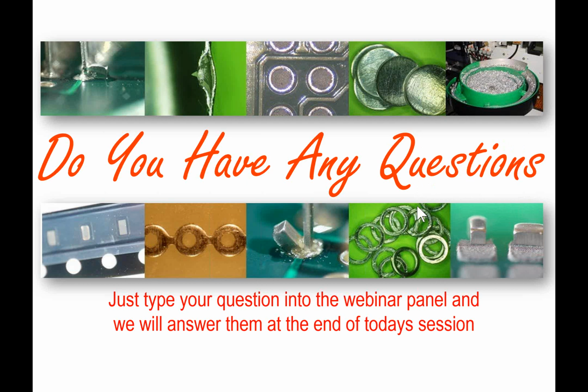No, I've not seen it as much of an issue, but I don't think the temperature banding could have an interest in the solder balls or beading here. It could be mechanics of the reflow profile, depending on whatever they're doing. Yeah, it's not specific. It's difficult to assess without a photo, but it could be that the process is slightly too low, or it could be an interaction with the solder resist again, where the solder isn't allowed to coalesce in such a way, or it could be just the volume is too great and there's an overspill based on the design of the PCB.